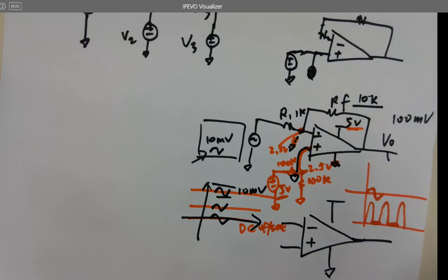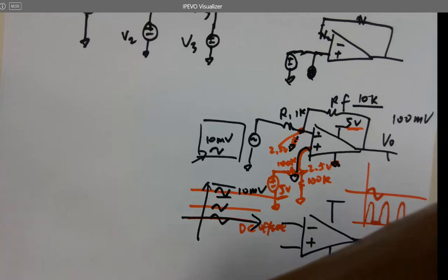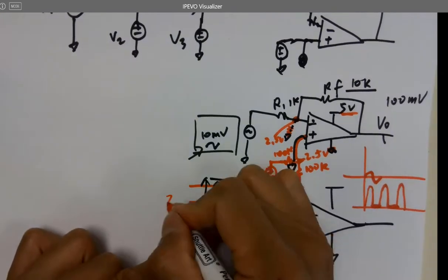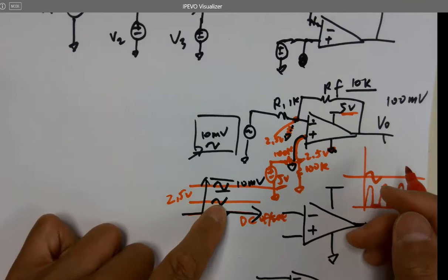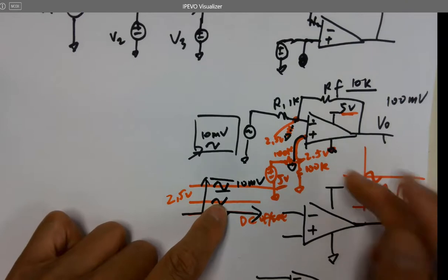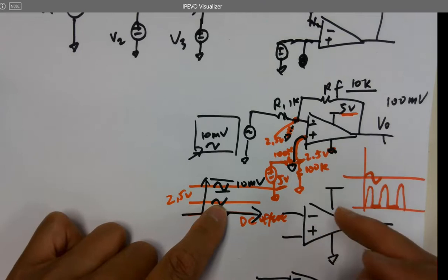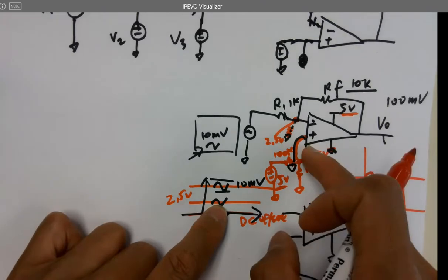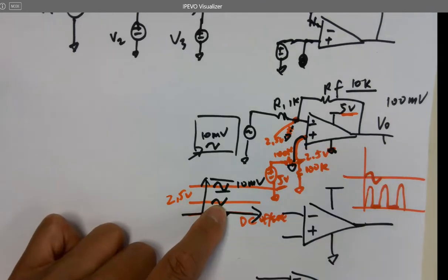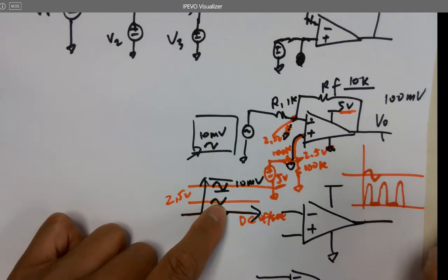Then what? Add them together. So you get the AC voltage lifted by the 2.5 volts DC. That's called superposition. That's why superposition is so important. You have to understand superposition first, then to understand op-amp and also DAC, right? So this is number one, the most important one in circuit theory.